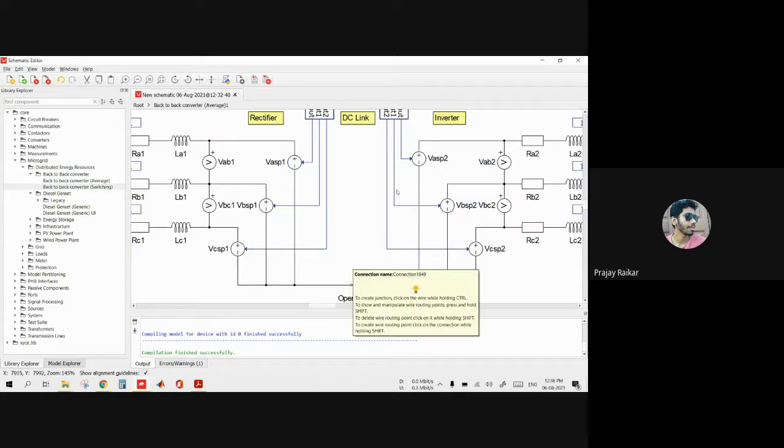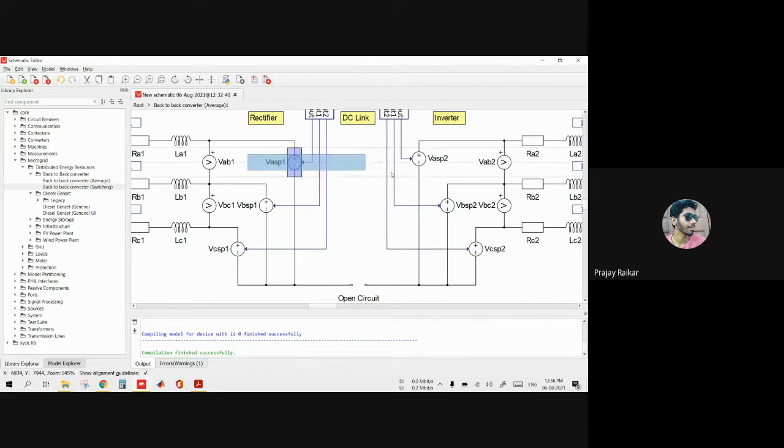Okay, so that's why, depending on whether you are designing a controller for the inverter or designing a controller for the microgrid, you are going to adopt either the switching type model or an average model. Like this, average models are more suitable for designing the components on the microgrid side. Okay, if you're designing a controller for a microgrid, wherein the detailed waveforms are not required for the converters.